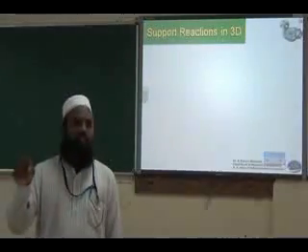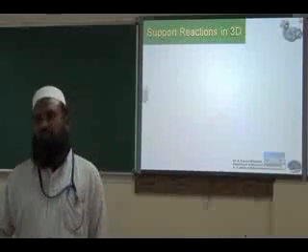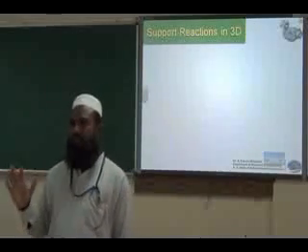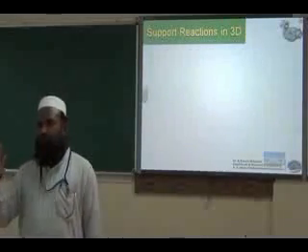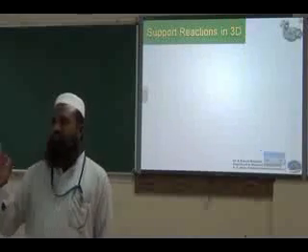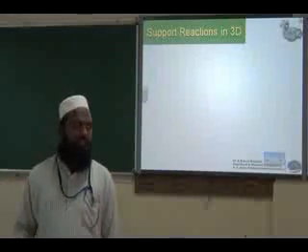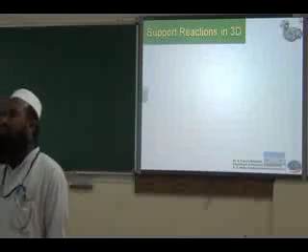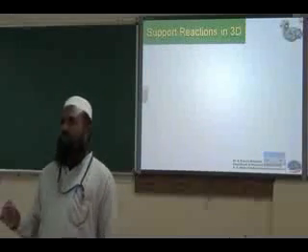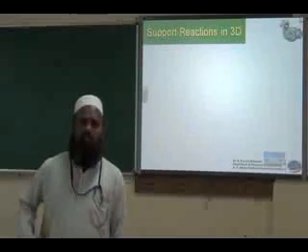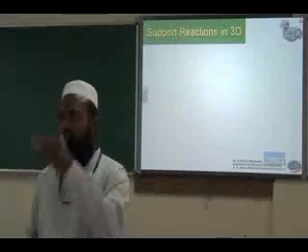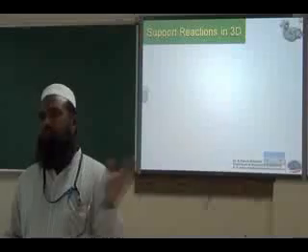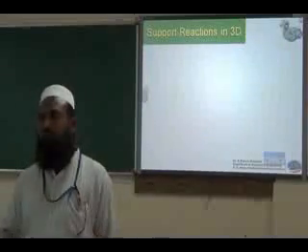When you arrest these motions, you will have support reactions. Generally, we can have a maximum of 6 reactions: 3 reactive forces and 3 moments. So we will say that there are 6 equations of equilibrium. Sigma Fx equals 0, sigma Fy equals 0 and sigma Fz equals 0, the 3 forces, because of no translation.